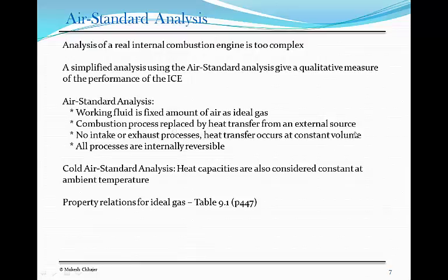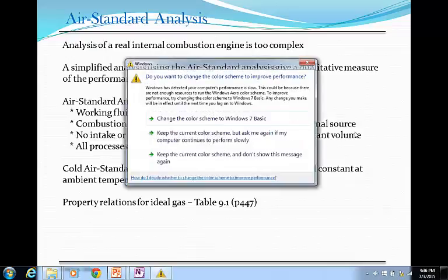So what we are saying is that instead of saying air is taken in and then after it burns is thrown out, which would make it a control volume system, because now we have mass coming in and mass going out, to again simplify it, we are just going to assume that the same air gets circulated, so it becomes a closed system rather than an open system.